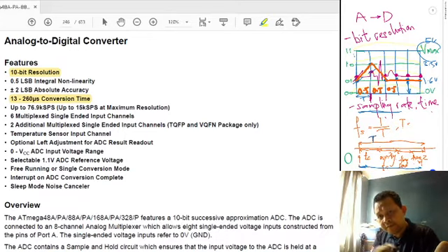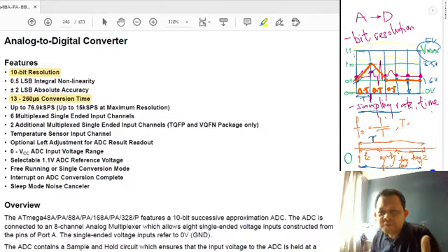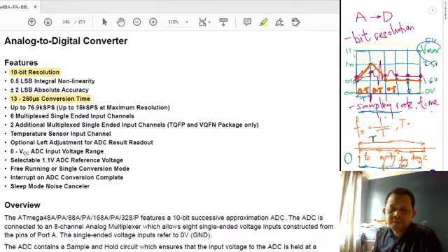So you have time to send from your microprocessor board to the display board, and then maybe the display board needs time to plot, and then another time, and that's why you have your total time over here, right? So that T over here. So if the conversion time over here in the datasheet does not include everything yet, you need to consider other processing times also.